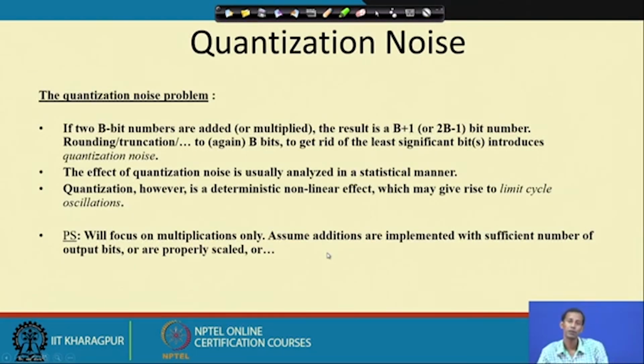So, in fixed point number representation, the terms associated are these. If we discard the MSB, we will get overflow error, that means we get the magnitude result in a wrong way. If we discard the LSB, we will get quantization error. For that I need to find out the optimum word length, keeping in mind that both performance and cost should be optimal. For what word length is it maximized in both cases? That is the optimum word length. While we are doing this floating point to fixed point conversion, we have to remember these things.